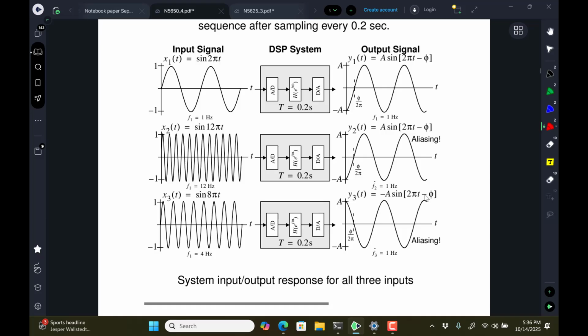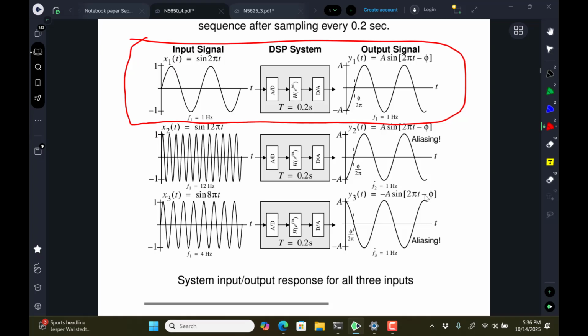The obvious choice, though, is to not purposefully let signals in that are above the Nyquist rate. So it behaves the way you'd expect. The digital system on the inside can now be programmed, and you can change algorithms. You could change the shape of the filter, the phase shift, magnitude and phase, and make the behavior a programmable system rather than electronic components.